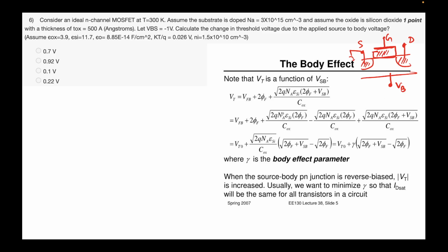How does it happen actually? So it's straightforward. This is the expression of the threshold voltage that we have. V flat band, as we know. 2 phi f is to denote the onset of strong inversion, which is the definition of threshold. And the next term that we have is basically coming from the depletion charge. We know that is the depletion charge expression that it is coming from.